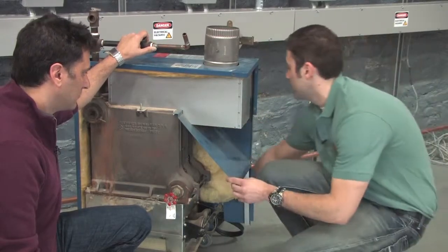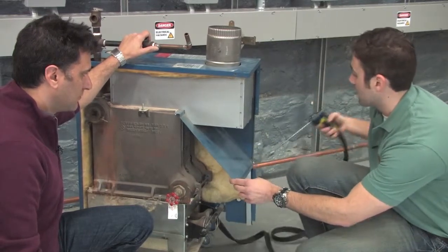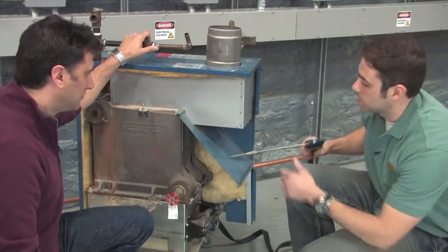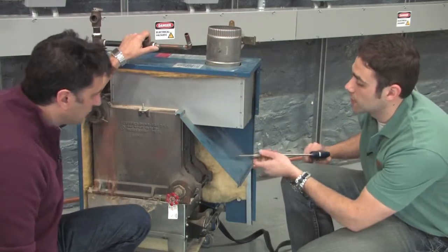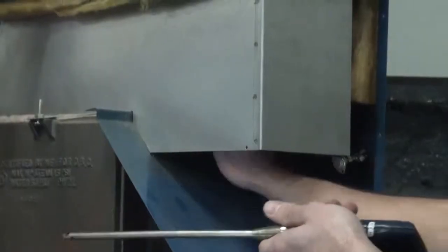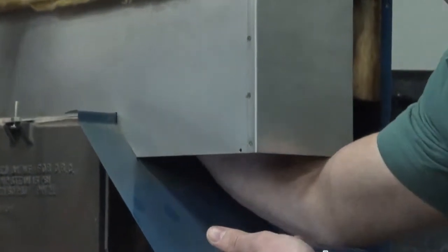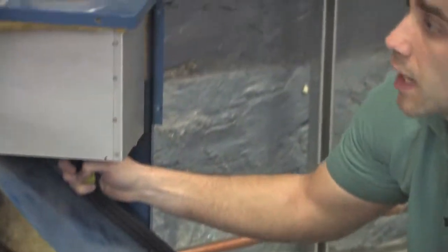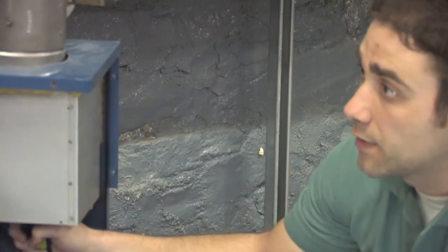So when we do our combustion efficiency test and we have our probe, we can't drill a hole in the flue pipe and test up here. It's already diluted. It's already diluted because the air is coming in. We have to get to the top of the heat exchanger and test up there. So this one, if you put your hand up here and went up to the top, you can feel the tops of the heat exchangers. And this probe is long enough that it can get up inside here, and we can test inside right at the outlet of the heat exchanger.